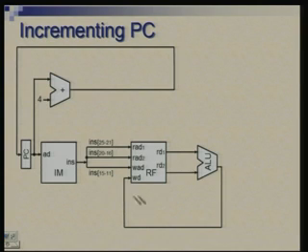So, you give, let us say at time t the output of PC was available for a new instruction, and then at time t plus 1, I am counting time in terms of clock cycles, not in nanoseconds now. So, at time t plus 1, which is the next clock, you get a trigger here and a trigger there.